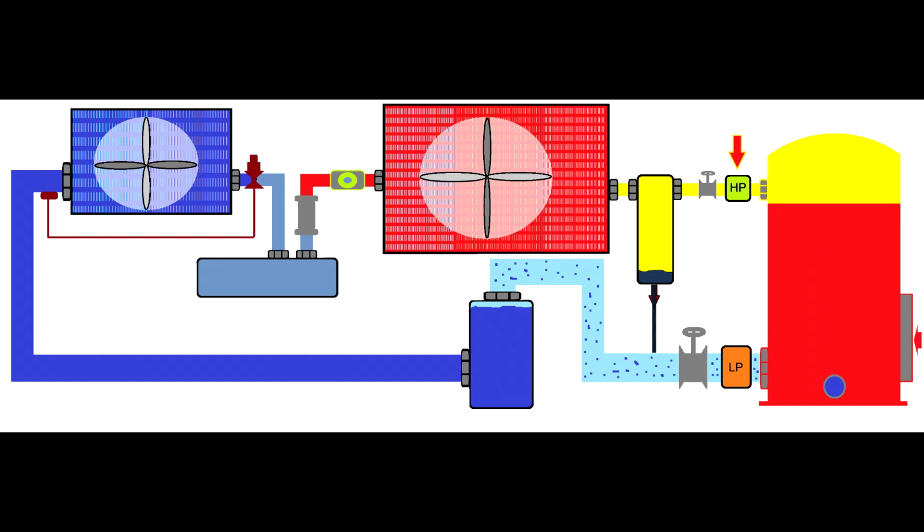If you overcharge the system, you will have a very bad surprise. Your system becomes inefficient, and a lot of liquid will return into the crankcase. You will sweep the oil from the crankcase and push it into the condenser.